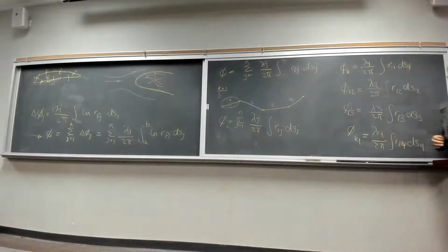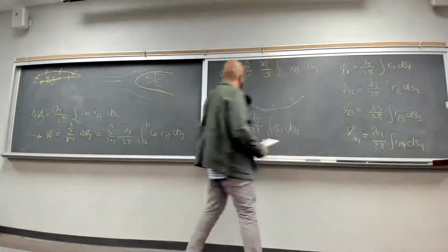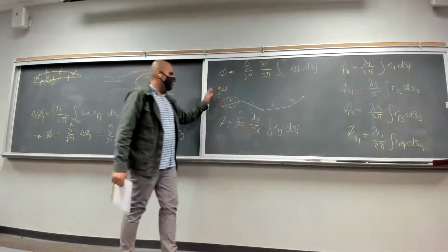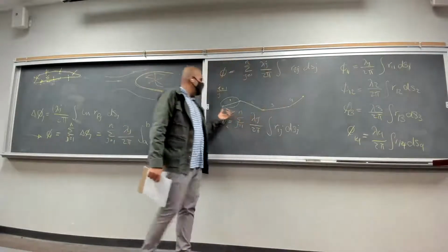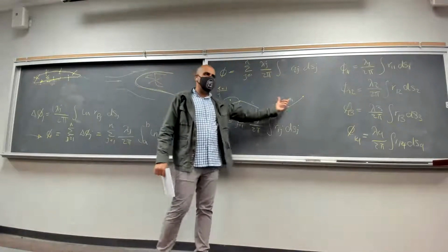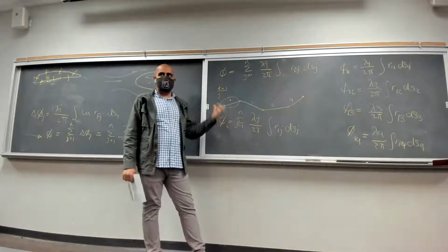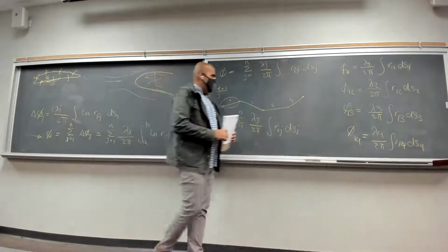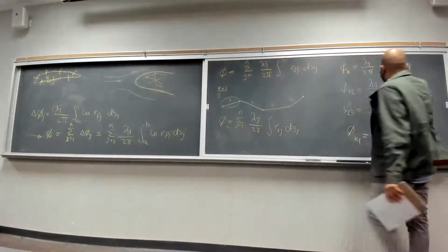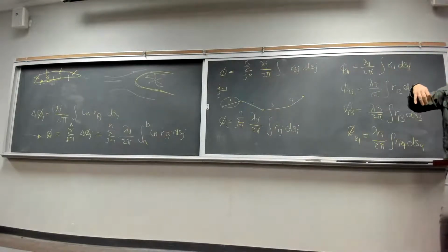Okay? So this is what this equation means. If you keep I as 1, we are going to find all of these phi's, velocity potential, that are induced at this panel 1 by these other panels and also itself. And we will talk about the velocity induced on a panel by itself later, because this value is going to be 0. There's no distance between the center of panel and itself.